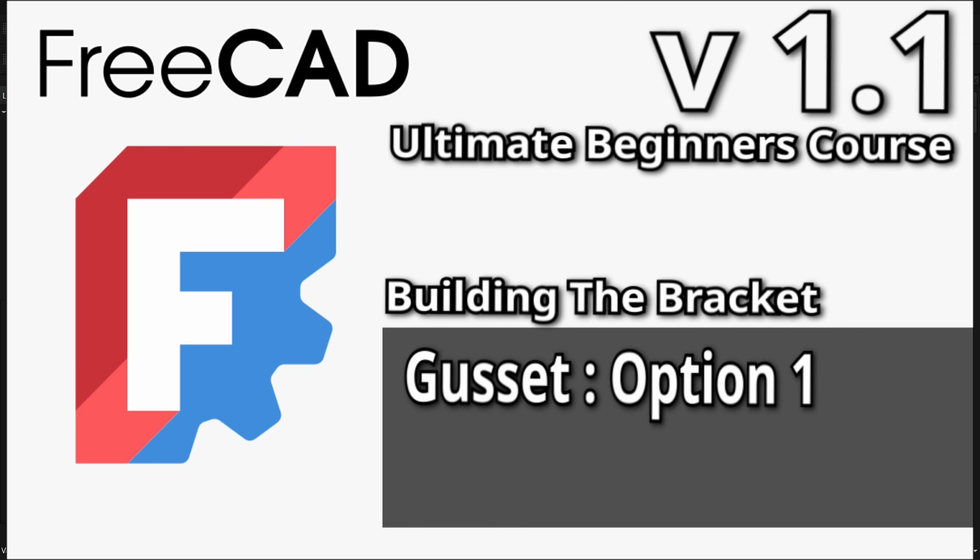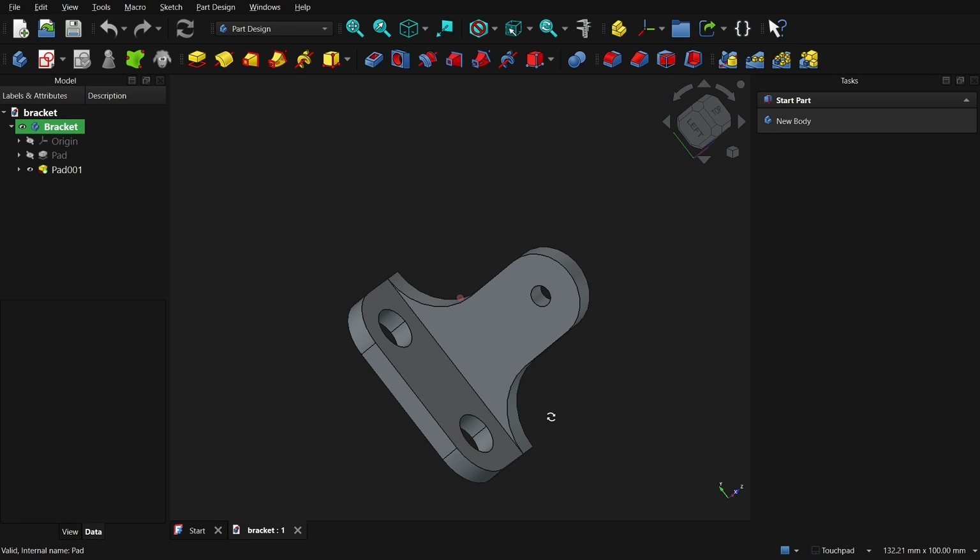Though ribs and gussets don't have a dedicated operation in FreeCAD, they can still be modelled quite easily. We'll take a slightly longer route first. This will help demonstrate how profile selection affects the build and allows us to explore a dress-up operation. The chamfer. Before showing a quicker and cleaner solution, let's start by selecting the face where the gusset will run